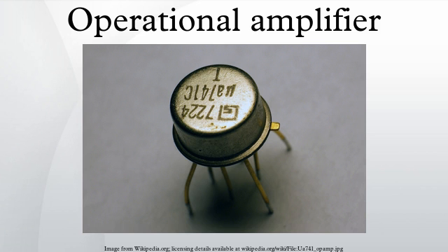Operation. The amplifier's differential inputs consist of a non-inverting input with voltage V+ and an inverting input with voltage V−. Ideally, the op-amp amplifies only the difference in voltage between the two, which is called the differential input voltage. The output voltage of the op-amp Vout is given by the equation, where AOL is the open loop gain of the amplifier.